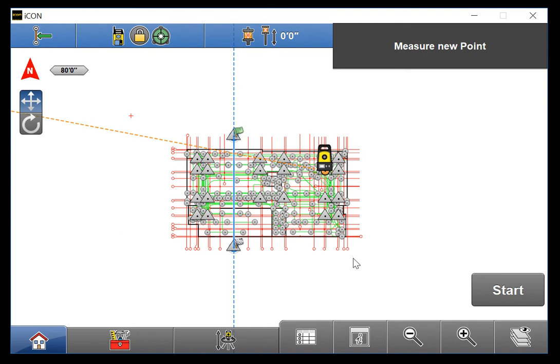In order to use this program to its full potential, it is necessary to explain how lines are interpreted in survey software first. Selecting any line in the background will result in the selected line turning blue, the appearance of a green flag and a black and white checkered flag, and the appearance of blue dashed lines extending from either flag in the direction of the selected line.